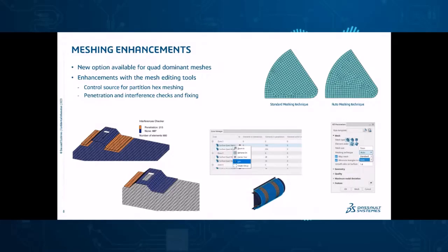And just to expand a little bit more on interference checks, there's an ongoing set of enhancements. If we look at the zone manager, there's some associated functionality for quick identification and fixing of those interferences. Things like filtering on mesh name, creating groups for the nodes that are causing the interference from the context menu. There's direct access to the Edit Mesh app, whilst maintaining the interference check UI, and they're all aimed at simplifying that workflow to fix those digital penetrations.